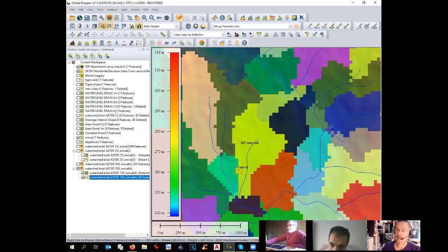Here you see how water will behave if you don't do anything. If this channel is in the right position, you can increase the quality of the channel, pave it, make a drainage system. If you don't want the channel here because you have a hospital, a road or whatever, then you have to dig and change the shape of your terrain to change the direction of the water. This is what will happen if nothing has been done on the field.